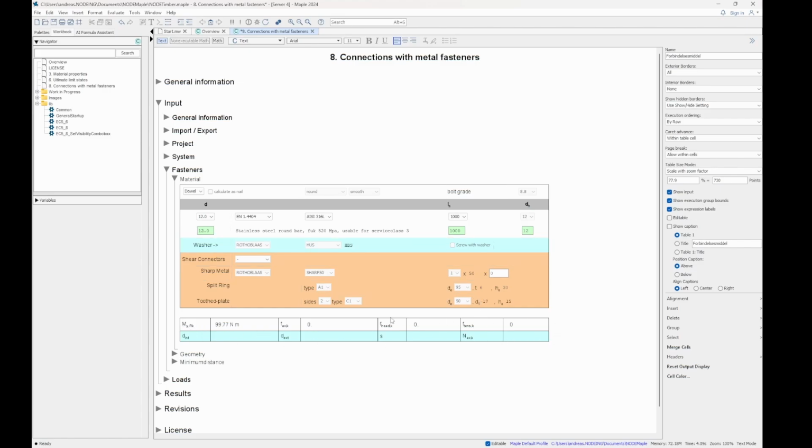This table here shows the material properties of the fastener itself: the MyRk, the moment resistance of the fastener, the axial capacity, the capacity of the head, and the tensile capacity. For other purposes, it might be interesting to have the internal diameter and the external diameter. This is regarding the washer, and also the capacity of the washer regarding the timber material.